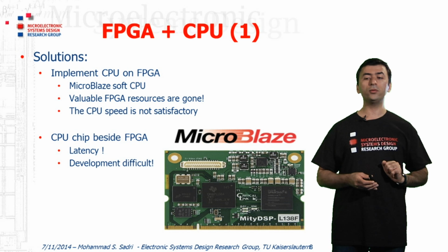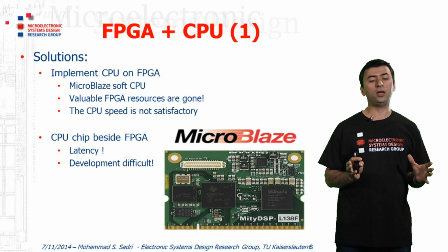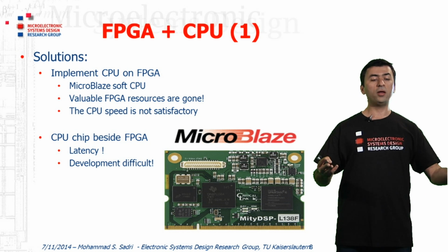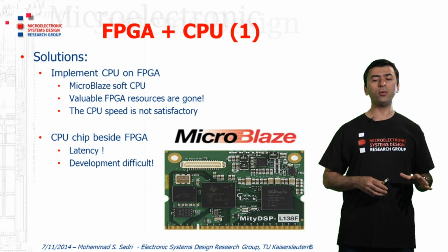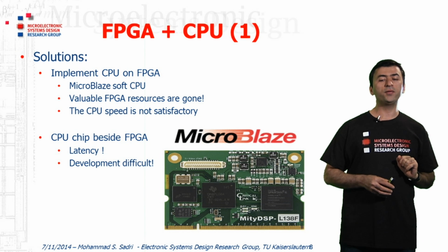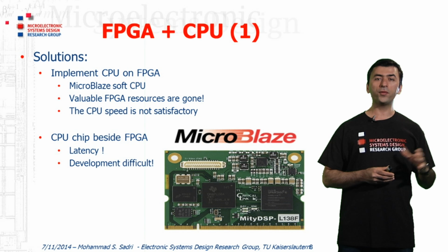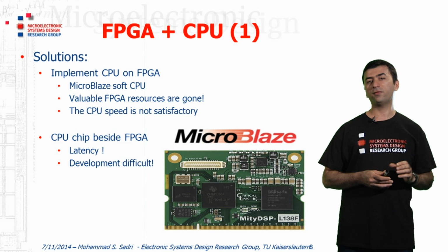Okay, one solution is, since the FPGA is providing us a sea of gates and we can realize any kind of hardware using an FPGA, one solution is we implement our CPU core as a part of the FPGA logic.